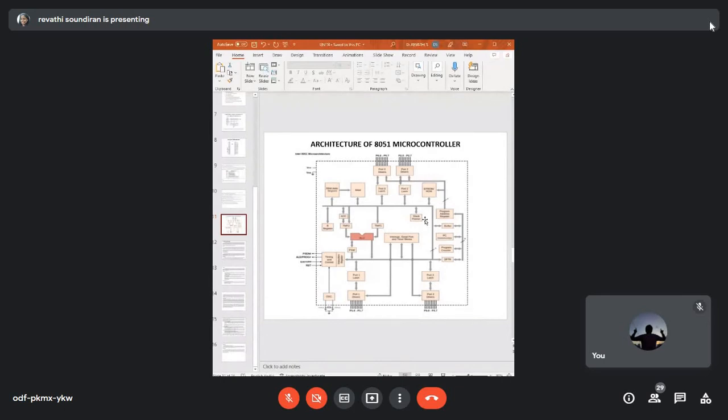In case it is going to address that subroutine or interrupt, it has to store the last value that it was working with. That is stored in the stack pointer. Upon storing in the stack pointer, it will go address the interrupt or execute the subroutine, and it will retrieve back from the stack pointer the previous instruction where it was in the main program, and continue the process in the main program.